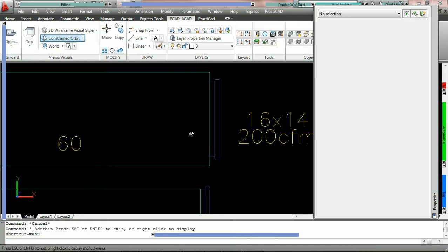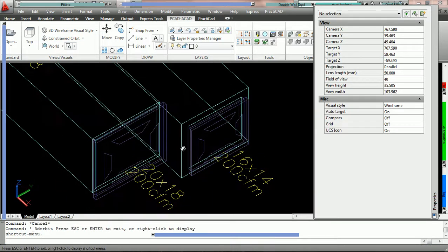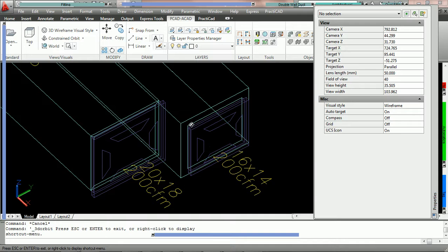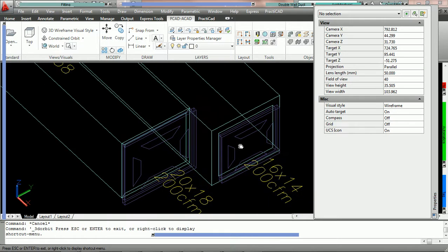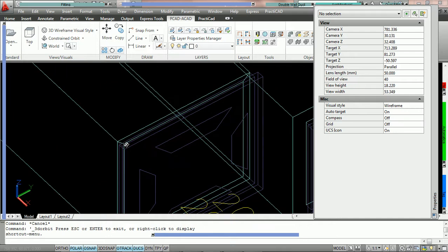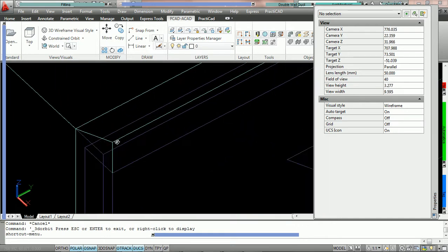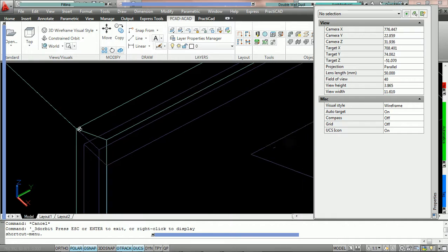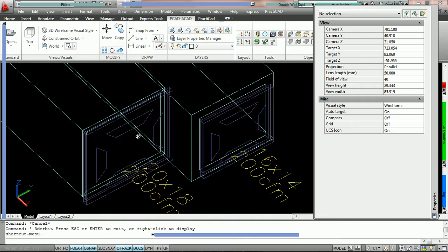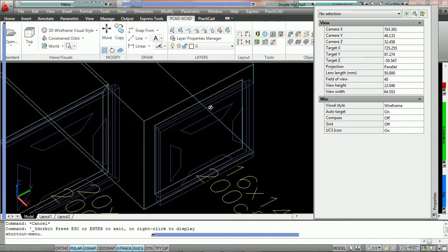What it's doing, if we put this in orbit, is actually snapping to the inside flange, or the connector flange. Notice here that on the one on the left, if you zoom in, you do have an inside flange appearance. But you can see if you follow this blue line that it's actually attaching the grill to the outer walls of the duct. However, with the connector flange parameter, when you snap a grill, it snaps the neck to the inside of the connector flange parameter.